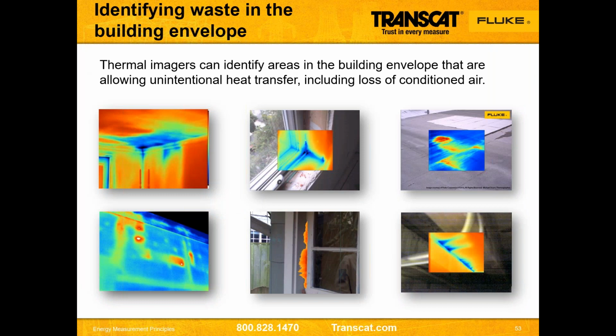So you can even find the leak on the roof. So we can find the origin of the leak. Where is the water contained inside of my roof under the substrates of the roof, and where is it leaking from? To just fix that part of the roof. We don't have to do the whole roof, just the part that's leaking. And we can certainly see that and mark that out with a paint gun with the use of a thermal